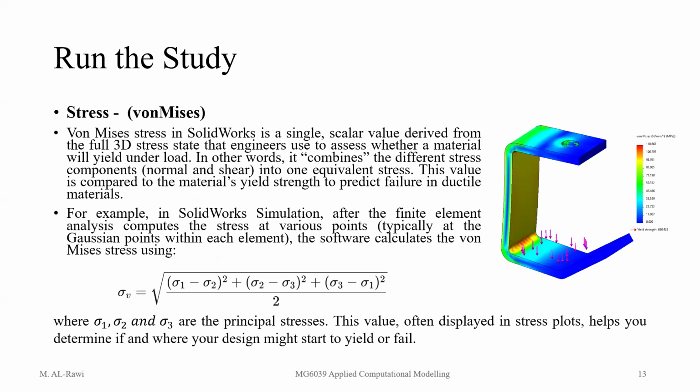So what is it showing you here? The design for that alloy steel has a yield strength of 620. Your maximum stress is 118. So we never exceeded the maximum allowable stress, so my design is safe. And what else? If you want to get rid of this +2, double click again and go to that. Instead of scientific, make it floating. And then tick OK, and that will change it to the right number.